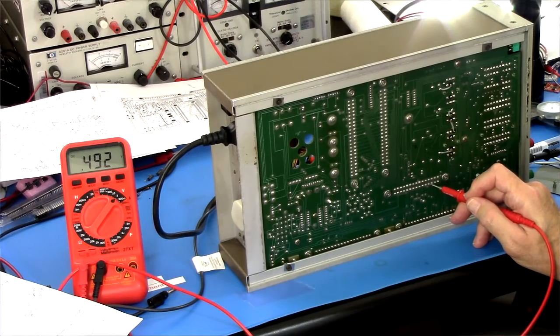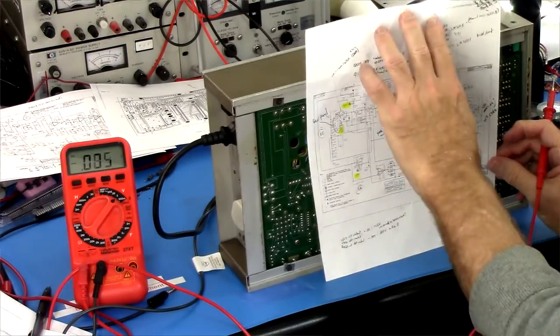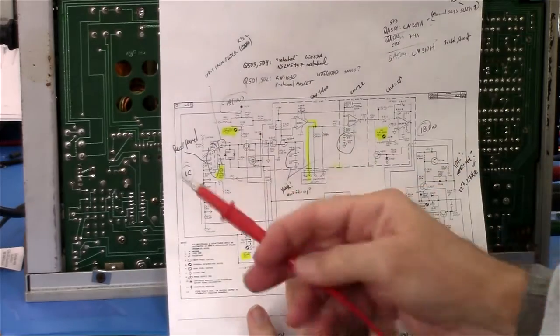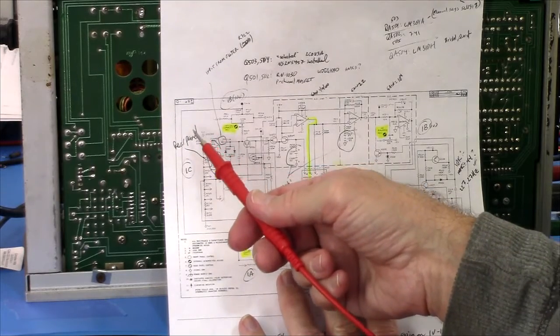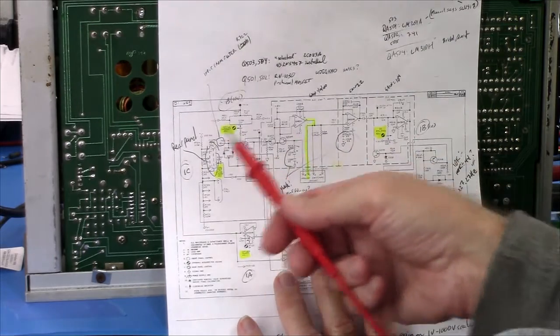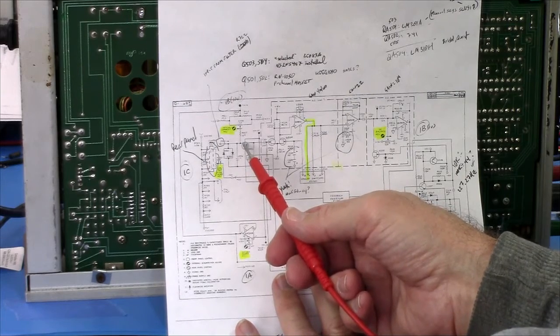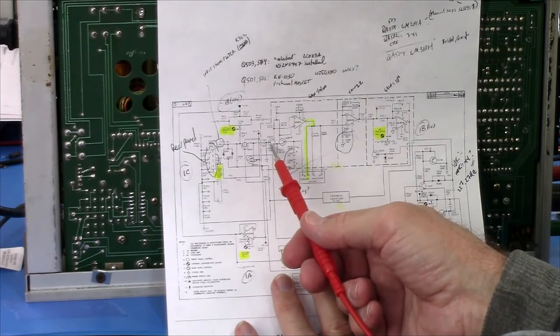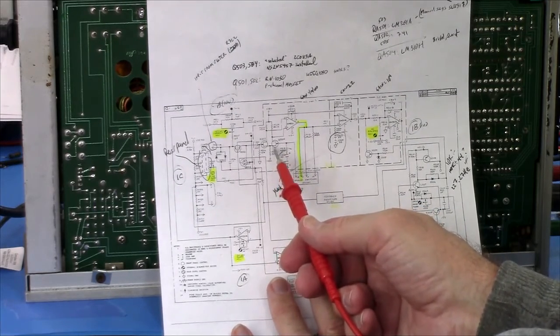Okay, what do you got? Oh, 0.492 volts. Well, that looks like a problem because looking back at this, the input is going to be 0 because I have that shorting bar on there. So that's basically a direct path in through switches and resistors and stuff. So there should be 0 volts coming into here, which goes to this side of the differential amp there.